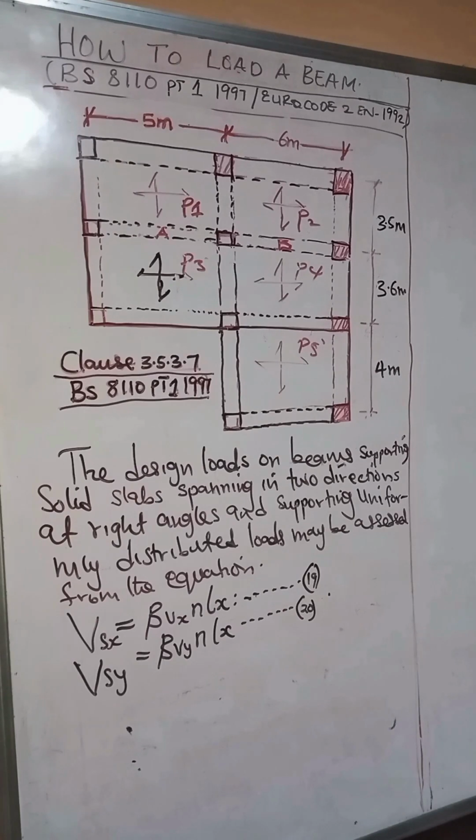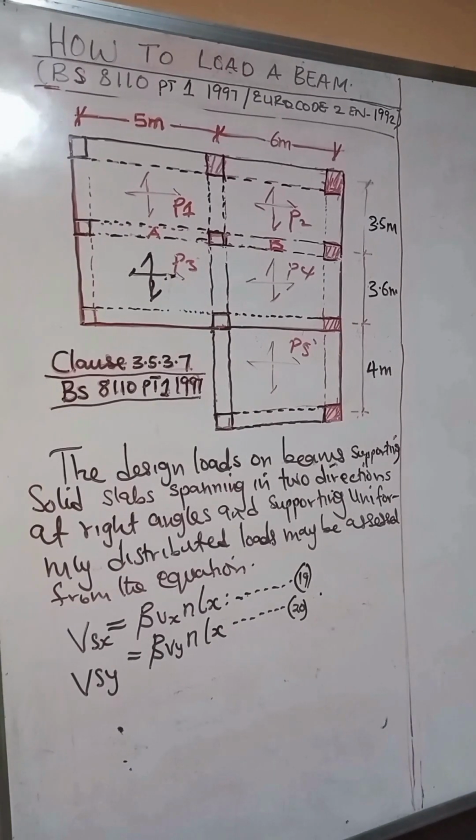Now, when we want to load this beam, we must consider two things. Number one, for the shear force expression, the load expression Vx is used. But the code of practice equally states that in applying this load on your beam, you must ensure that the load is applied at the center of the beam in such a way that the load occupies 75% of the total span of that beam, placed at the center of the beam.